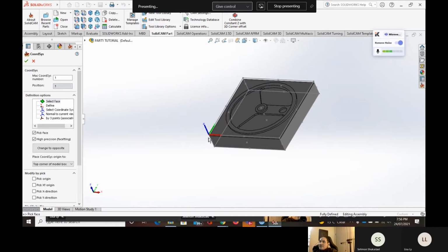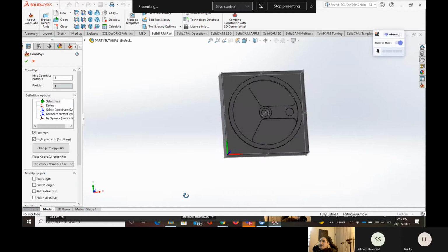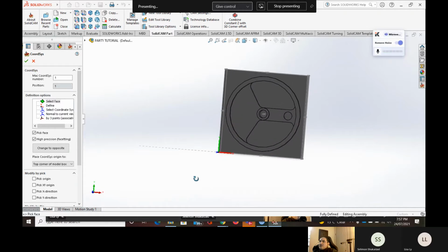So for example, this will be the end of the fixed jaw of the vise. So it's always going to be my reference. So I can fix the part here, and I'm going to be sure that this will be the datum point, and all the machining will be done peacefully. When I say peacefully, I mean we're not going to have any contact with the jaw sides.